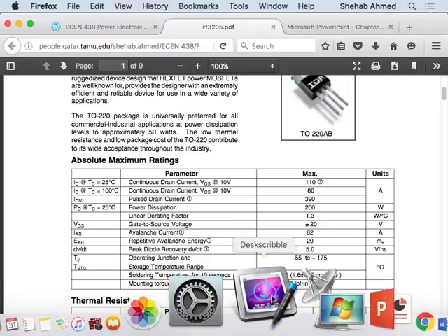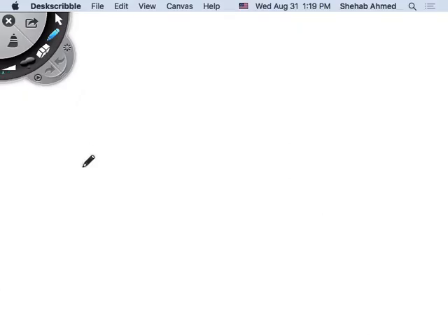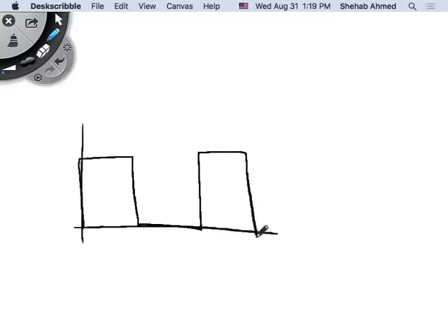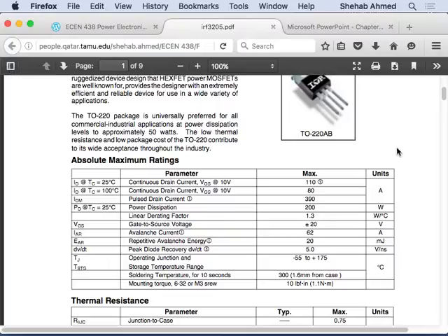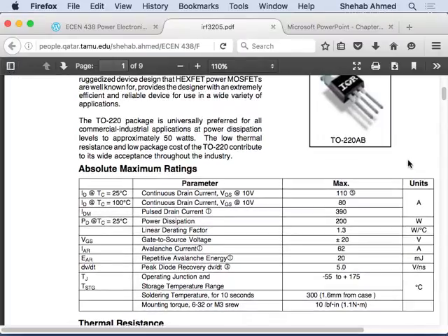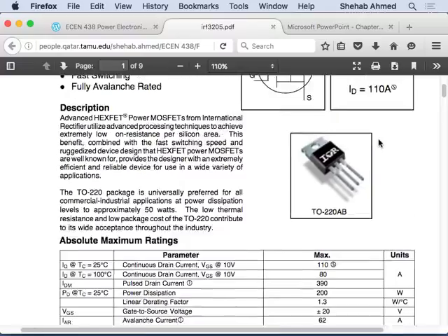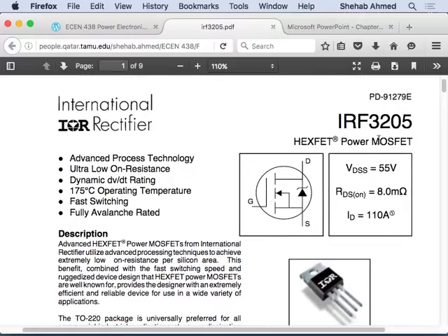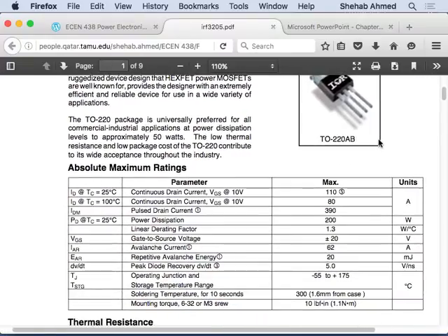When we were drawing this device turning on and turning off, I was drawing this rising in no time. This is rising from 0 volts to 9 volts, for example. But there's no such thing as no time, right? So actually, it will depend on the switch that you choose. This is one type of switch. This is a MOSFET. It just happens to be a MOSFET.